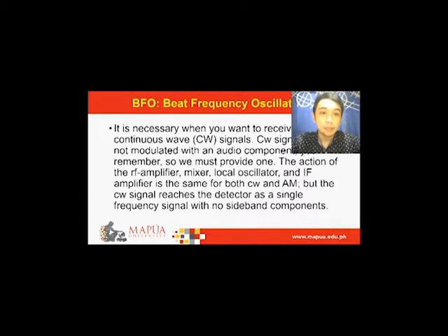So, the BFO, which is the beat frequency oscillator, is necessary when you want to receive continuous wave or CW signals. CW signals are not modulated with an audio component, so you must provide one.